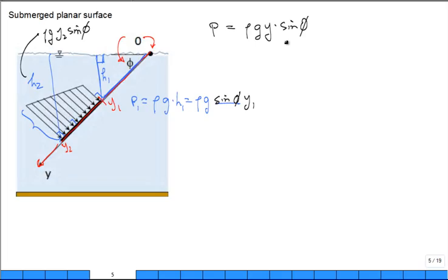So what is going to be my resultant force? Well, this is the pressure as a function of y. What I want is one resultant force, which is unknown, times the area of my plate. I didn't show that red area, that other view, but it's viewing it from this direction. Okay, you can imagine it's a rectangle. That's the area I'm talking about. It has to have a depth into the plate or into the sheet. It is equal to the integral of the pressure times dA.